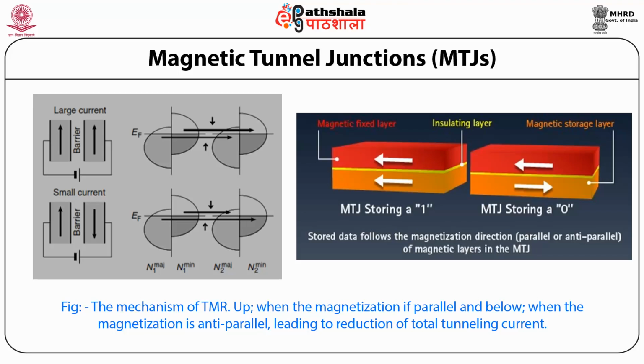This can be accomplished by several methods, which include, or sometimes combine, the use of intrinsic differences in magnetic hysteresis of ferromagnetic material, exchange biasing, antiferromagnetic thin film, and antiferromagnetic interlayer coupling across non-magnetic metallic film.